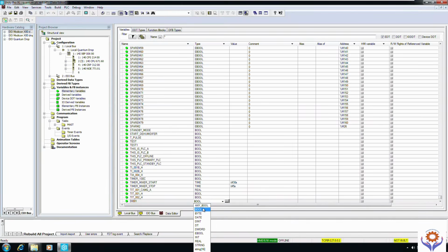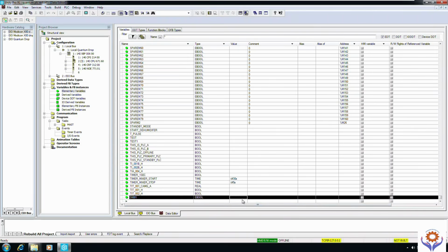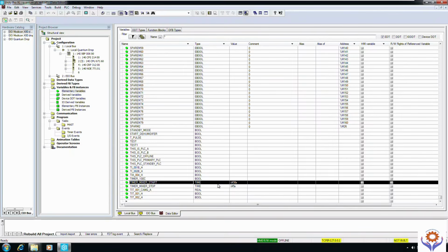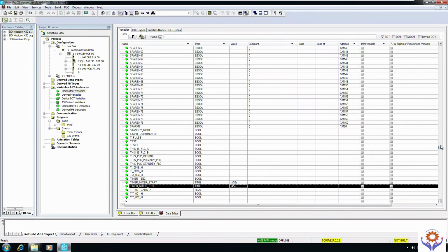EBOOL is used for any of the physical inputs. BOOL is for input like a system address, but EBOOL should be for any physical address. If you need to connect physically, for the digital inputs you have to consider EBOOL. And I am going to provide one address called %I1.2.0. Once you enter it, it will be directly mapped with the hardware. So this is the overview of how you need to configure the elementary variables in our projects.